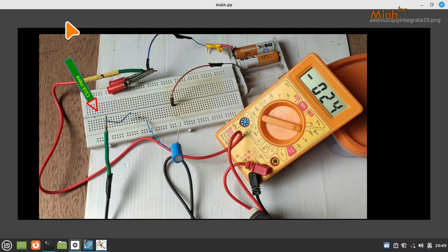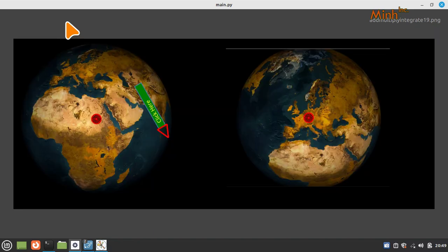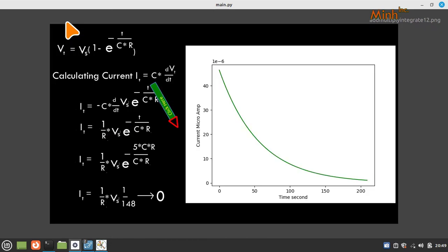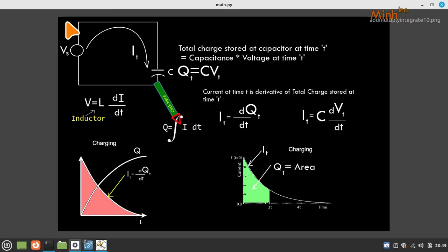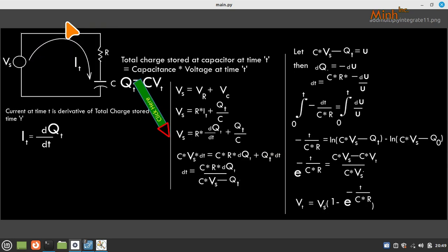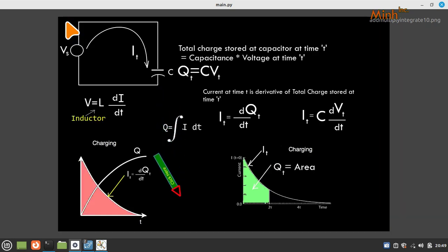In lab session 2, we saw finding the capacitance value or behavior of the capacitor, and that behavior of the capacitor follows integration, where at any moment the net charge stored is the integration of the current I at that moment. And if I know the I equation, then the area of I becomes Q, that is the fundamental.